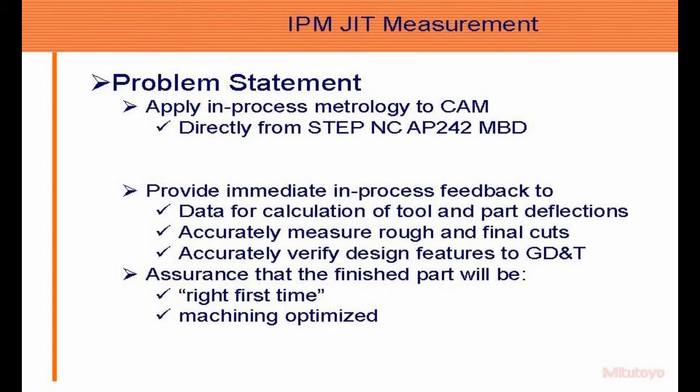So the problem statement is how to apply in-process metrology to CAM. What we're doing here is taking a model directly created from STEP-NC. It's an AP242 model, it's an in-process model. And we're going to provide immediate in-process feedback that can be used for datum calculation, for tool and part deflections.